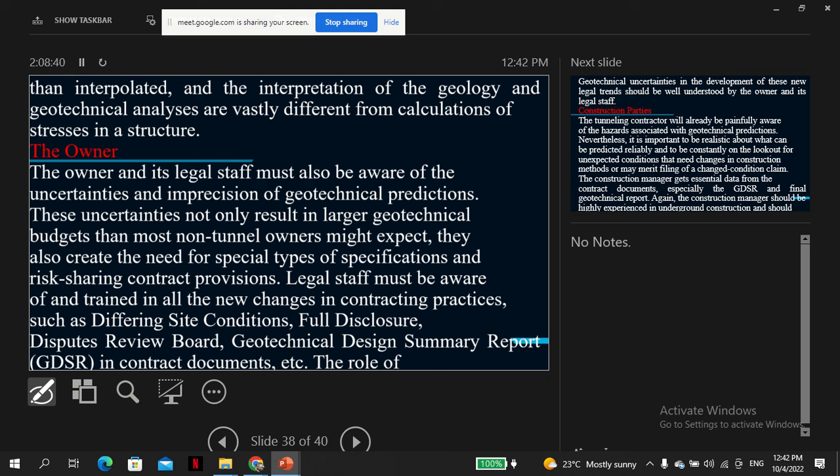So if you cannot continue digging to the depth that is required, and you're lucky to find rock, you note that, but you have to give them a recommendation on what can be done just in case this rock is not continuous to the required height. This was the idea. So this is where experience comes in. And now I've given you an example with the basic subsurface foundation. Now you can think of how much more complicated it is in a tunnel, where you don't see anything, but you use just isolated data. But this is the idea.